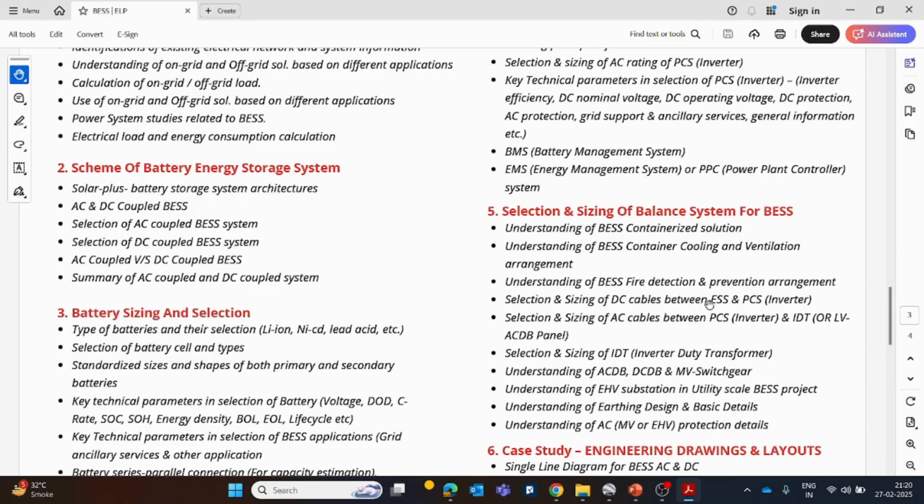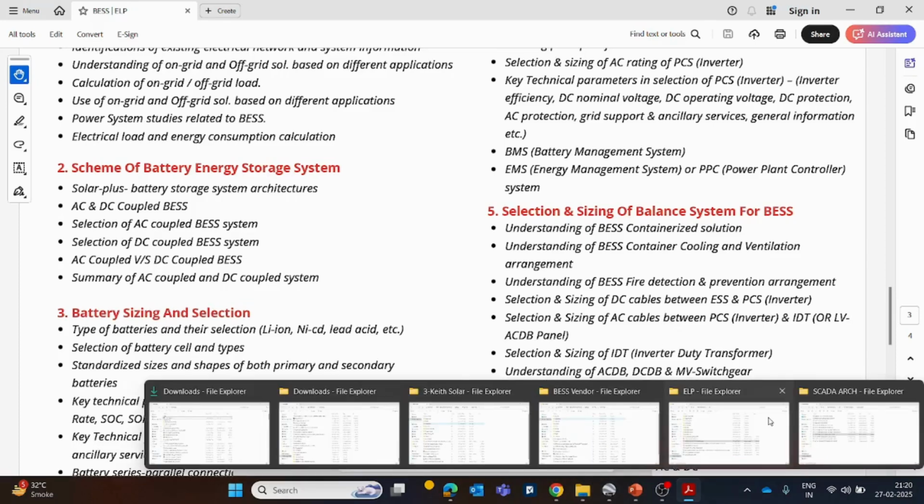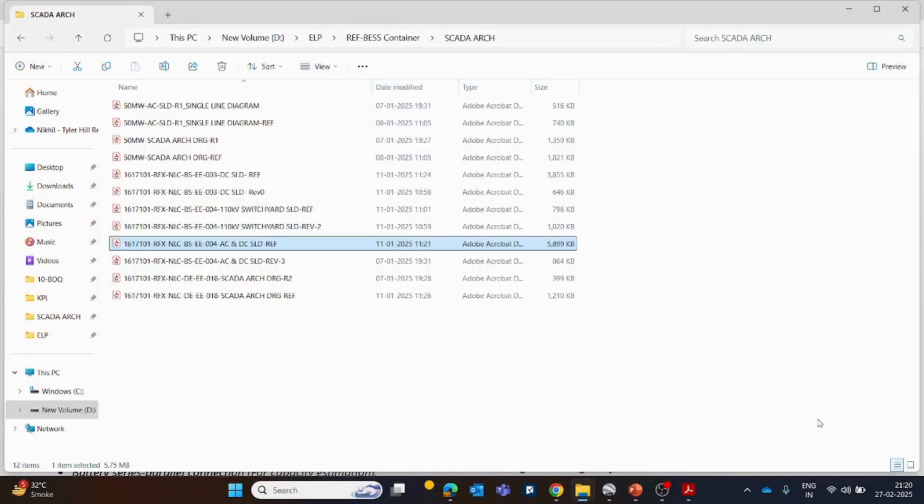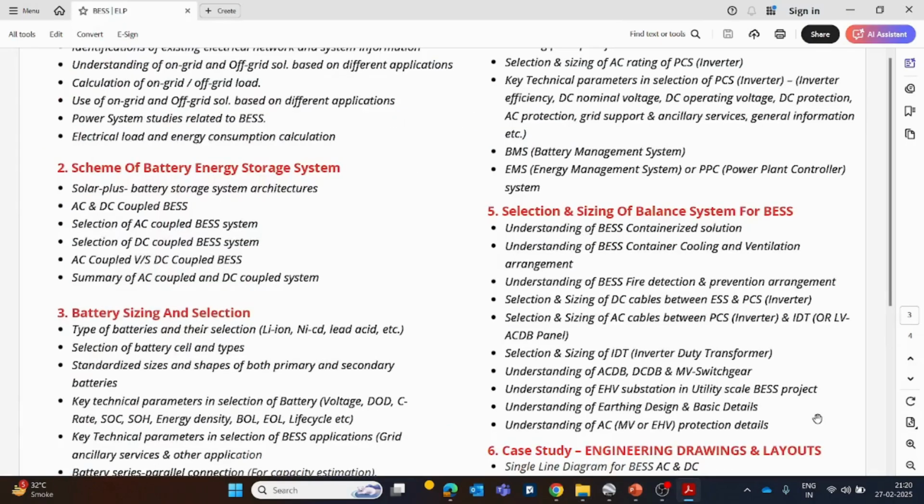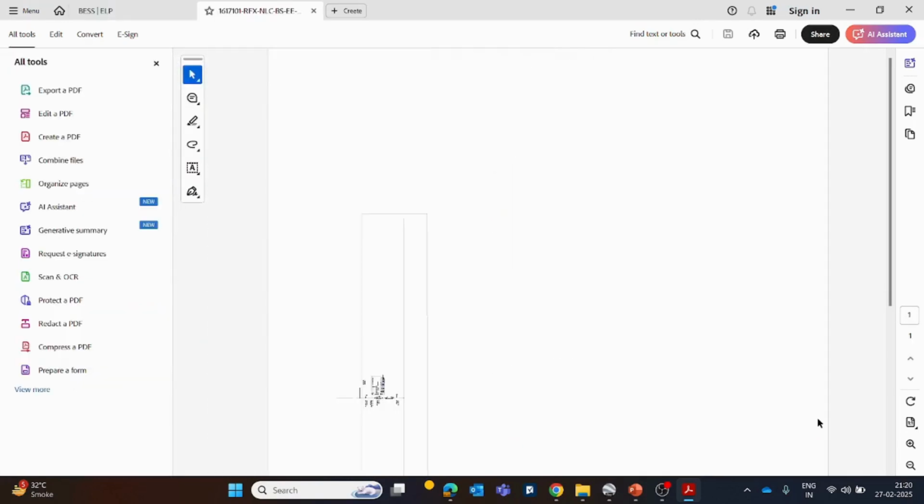If you haven't worked on cable sizing earlier, then I'll suggest that you keep practicing and gradually you'll be able to understand it, because it's not that tough a topic. The main thing to understand yesterday was that you should get an idea where you need to do cable sizing and where you probably need not. In case of PV, you have to do DC cable sizing at almost all locations, because you need to connect your strings to the combiner box, to the inverter, and then further from the inverter to other places.